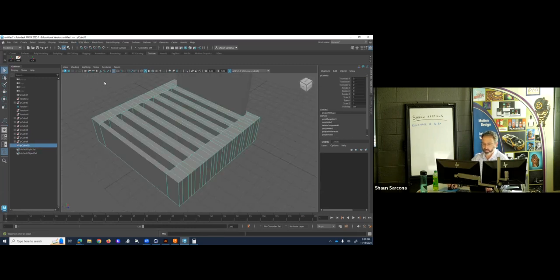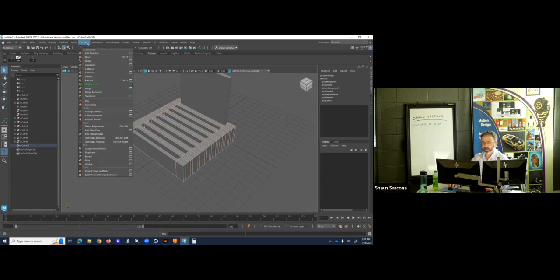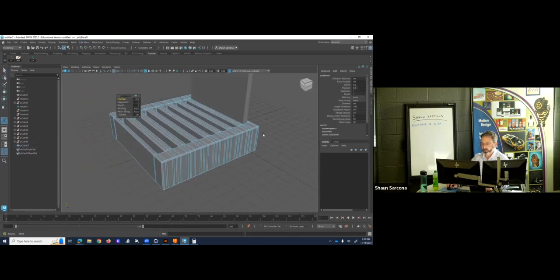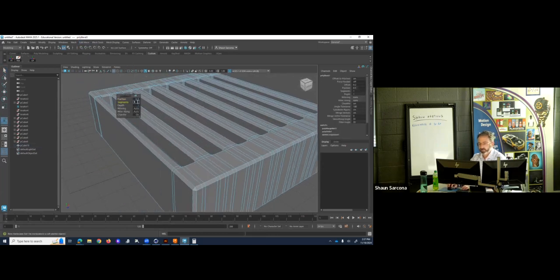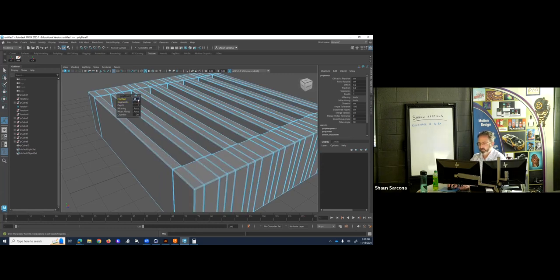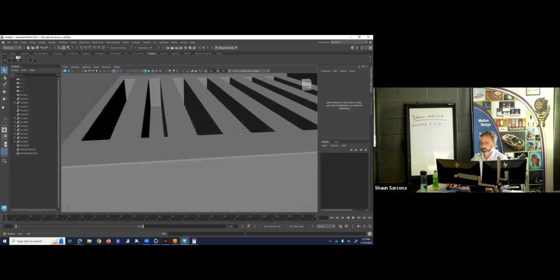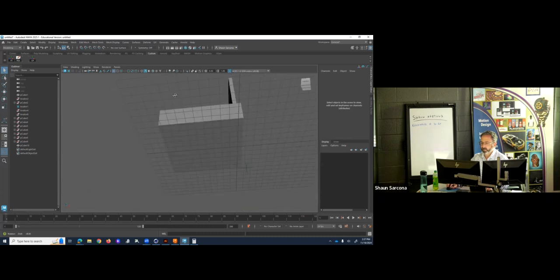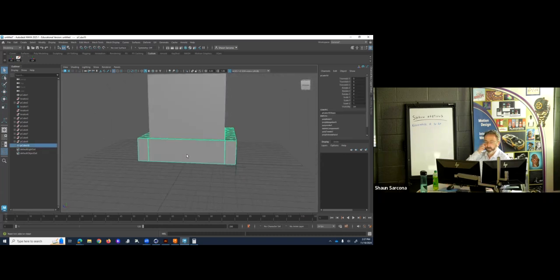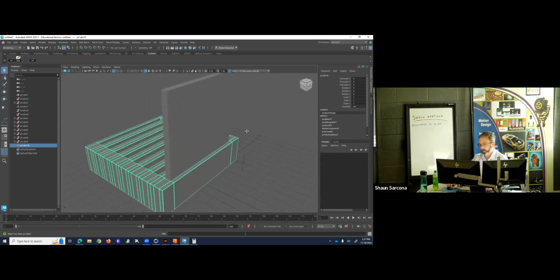Then same thing, bevels across everything. Grab it all. Let's throw a bevel on here. Let's go to 3.2. I think that should be good. That's done. Now, if I wanted to punch my name into the front of this, that part is a lot trickier in Maya because it doesn't have an ability just to cleanly punch stuff into it like a surface. So I won't be doing that inside here.